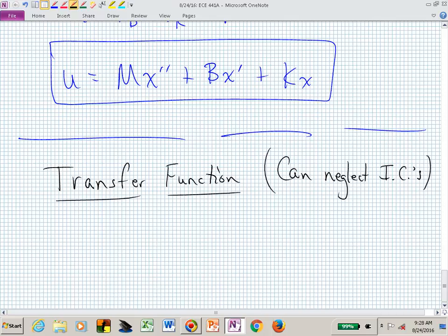That throws us into a very nice domain to play in, the frequency domain. And what can we use when we start talking frequency domain? And these are continuous time. These are not difference equations. This is a differential equation. Laplace transforms. Now we can put this from the time domain into the frequency domain via Laplace transforms. If I Laplace transform u of t, what does that produce? This is now just a generic time domain waveform, so I'll just say it's a generic frequency domain Laplace transformed quantity, capital U of s.